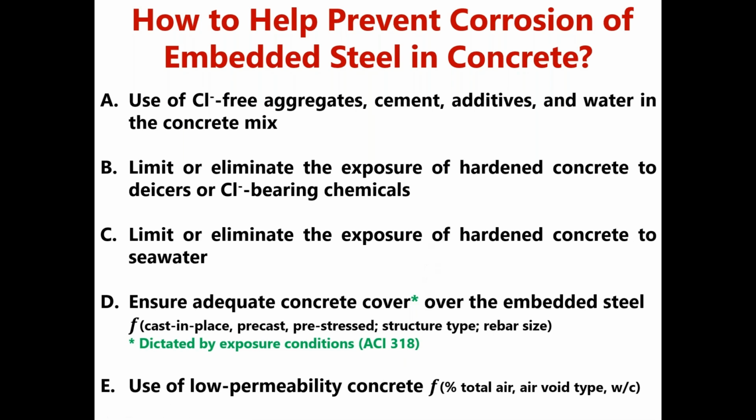And we all know that concrete is both porous and permeable, and the permeability and porosity is a function of how much air is in the concrete. Is it entrained air, entrapped air, and so on and so forth, the water cement ratio. So a lot of factors are going into that.